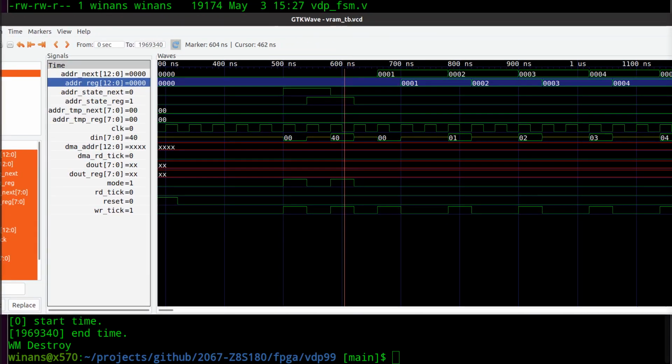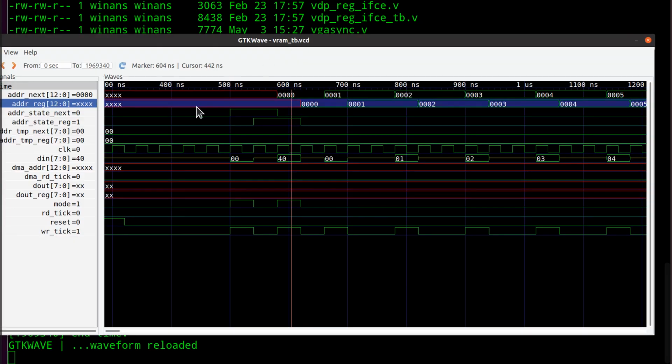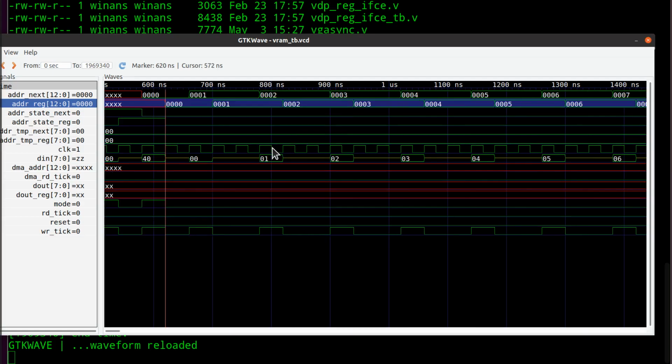That's this guy here, right? So now what it's doing is it's saying set the address to garbage when I do a reset. So that's why you can now see when the actual address register flips to 0, when this is high on the leading edge here after this second write tick. So that's how it got set to 0. Normally, if you set it to 0 and it's already 0, then you don't see the action taking place.